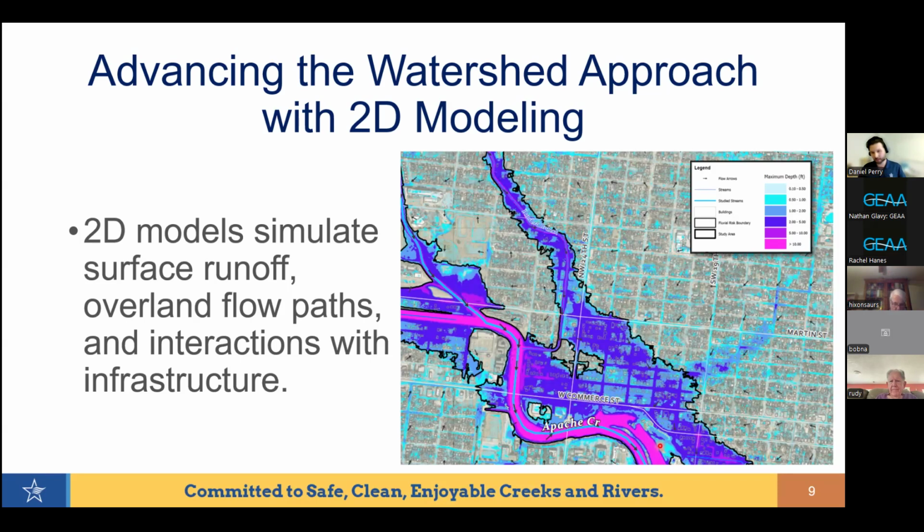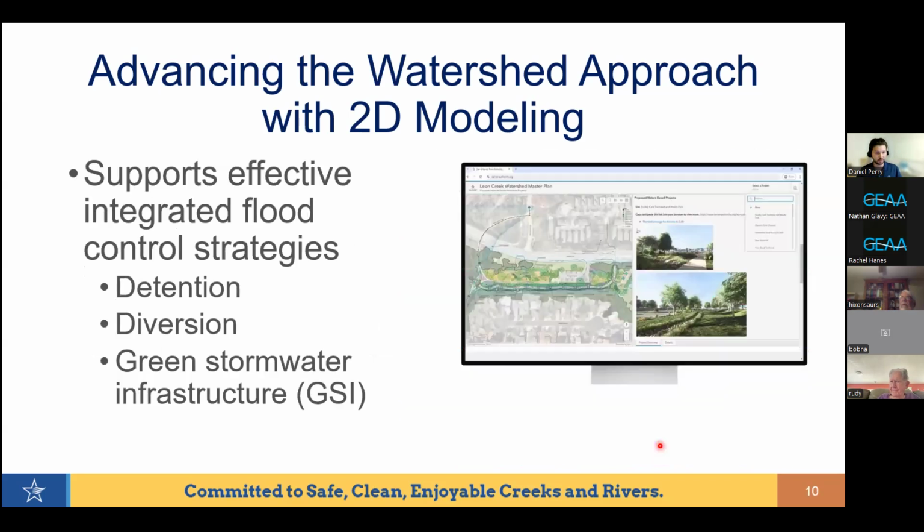And for our Westside Creeks model, we weren't able to incorporate storm drains. We used HEC-RAS, which at the time didn't have storm drain in the model itself, but we do hope to start incorporating it, and it will show a decrease in the floodplain when we do. It may show decreases in the urban area, but that could also mean increases along the channel because that's where a lot of the storm drains are going. This gives a much clearer picture of the flooding across the whole area and can help communities plan better and design more effective flood protection.